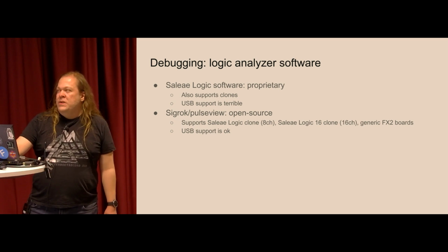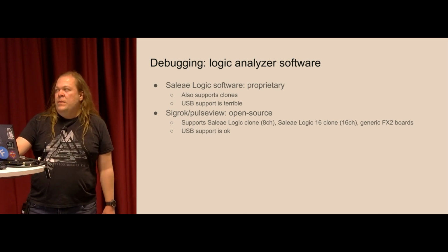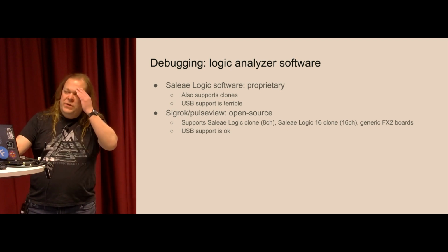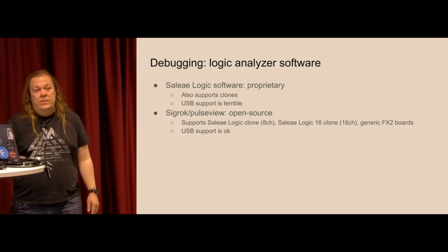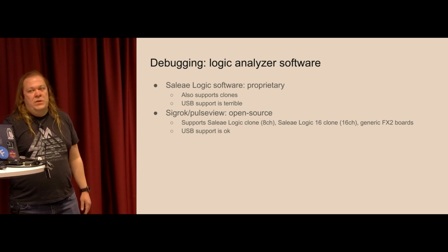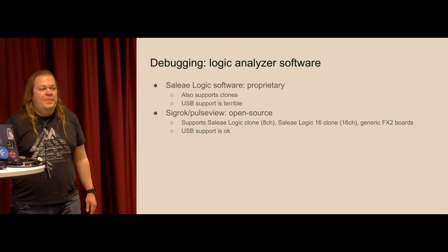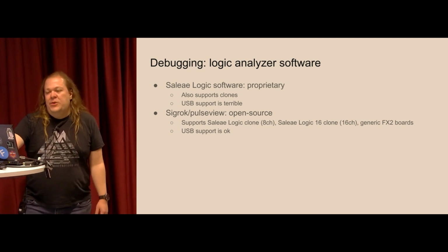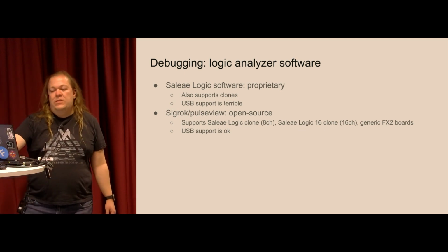Yeah, also I noticed that the latest version of the official logic software for some reason doesn't support export into VCD anymore. I remember that 1.x supports it, and I checked this, but 2.x for some reason doesn't. It supports CSV and some binary format. That's it. But yeah, it can be converted, of course, into VCD or something suitable for SIGROC.